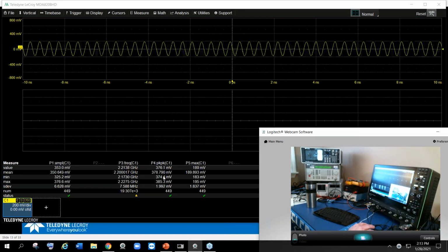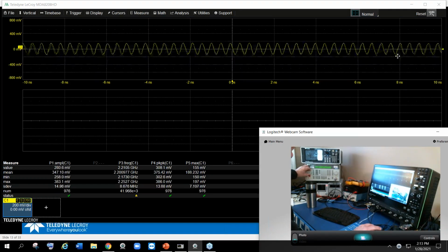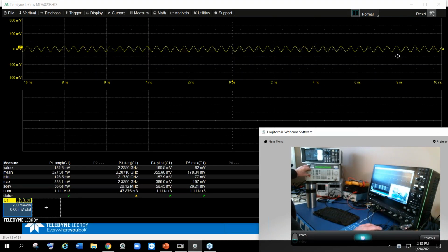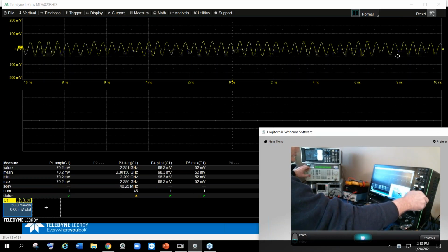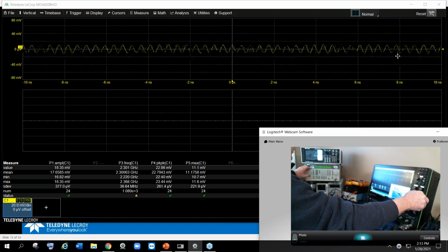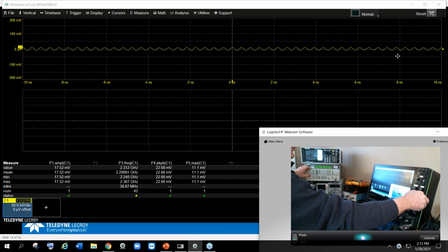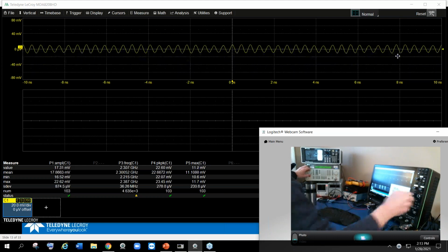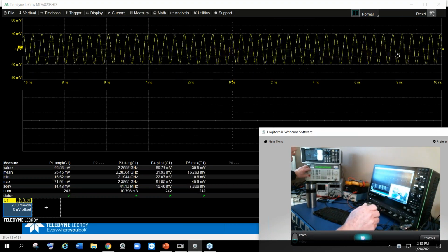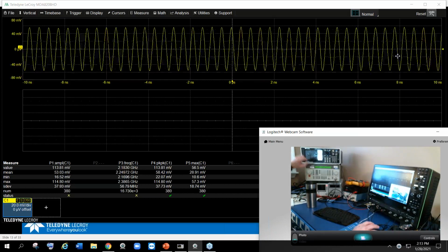We still see the waveform. We're still triggered on it. My trigger level is up to the top right here. But there's our signal. And so our 2 gig scope, we're pushing it. And I could change the amplitude on the amplifier too, by the way, right? So here's 2.3 gig. I could change the sensitivity if we wanted to. So we can still see the amplitude, but it's getting tough. So that's the roll-off that all scopes are faced with.